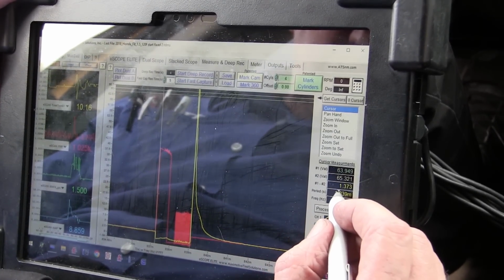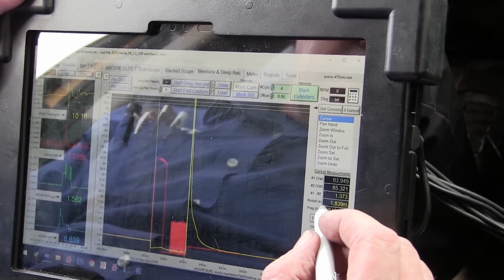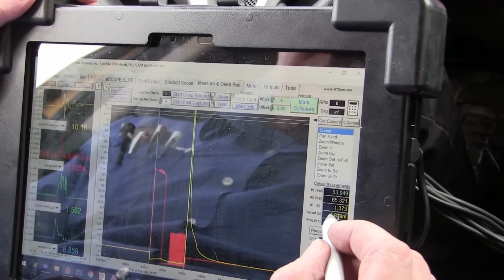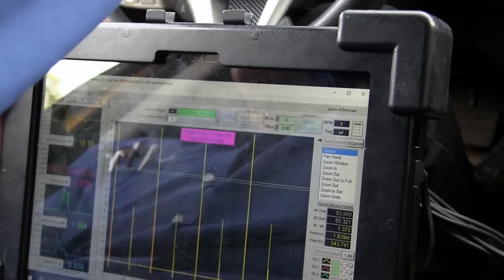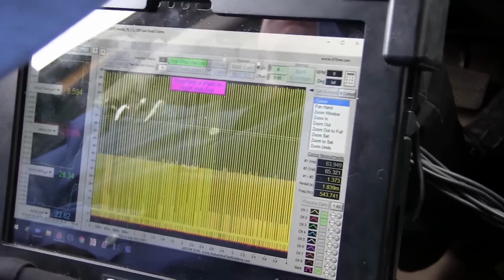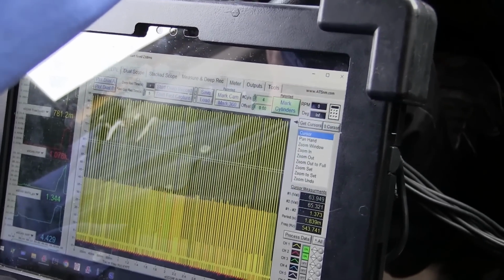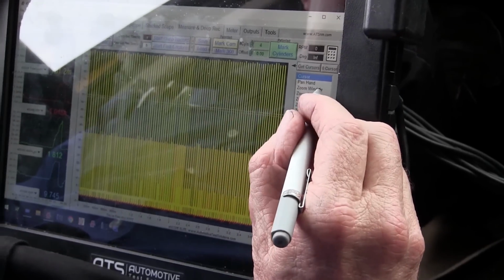Okay, so we have 1.8 milliseconds, so we're on for quite a while. This is more like the 16 I looked at that was 1.7, 1.8. Now we're there on our time, and we're not taking away a lot of trim. So now I want to put this thing under a light load like we did the other day. Okay, that's just a real moderate load. That's not wide open or anything, but that's just a good load on it. Pulling the weight of the car up, get our zoom window.